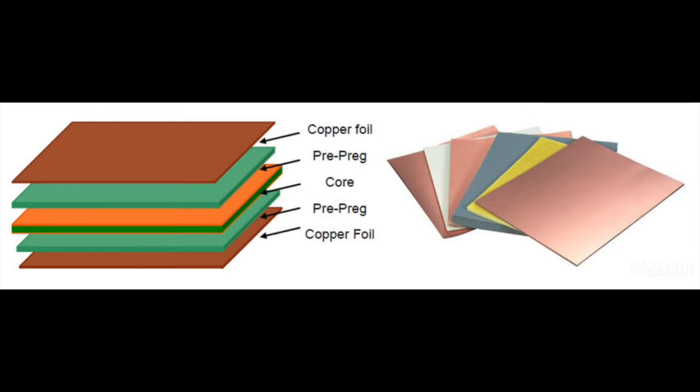So when you talked earlier about loss, now somebody as simple as me thinks the lower the loss, the higher the speed. Generally, yes, but the basic principle is that as frequencies increase, the interaction with the laminate material itself starts to increase, and it's this interaction that introduces the loss. There's also obviously conductor losses as frequency increases as well.